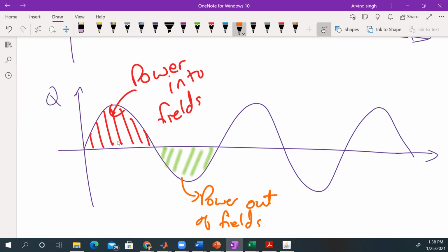And you could also transmit less power on the line because you will be transmitting a small amount of power, but you have a high current, which is going to heat up your line. And the lines have thermal limits, right? So that is why we always try to do power factor correction and keep our power factors very good, right? So that is the real and reactive power.